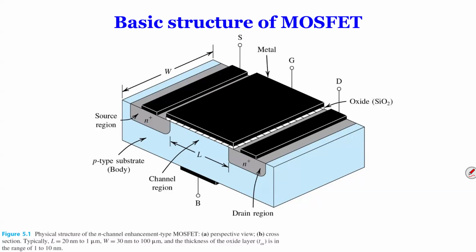So you can imagine that between this metal and this body, there's not going to be any current because there's an insulator in between. So there's actually no current flowing between the metal and here. So now you have metal oxide. You have metal connected on all the pieces, but especially in this area, we define this as a gate. You will see why it's called gate. So the gate is a metal. This is a flat piece, like a capacitor type of piece of metal.